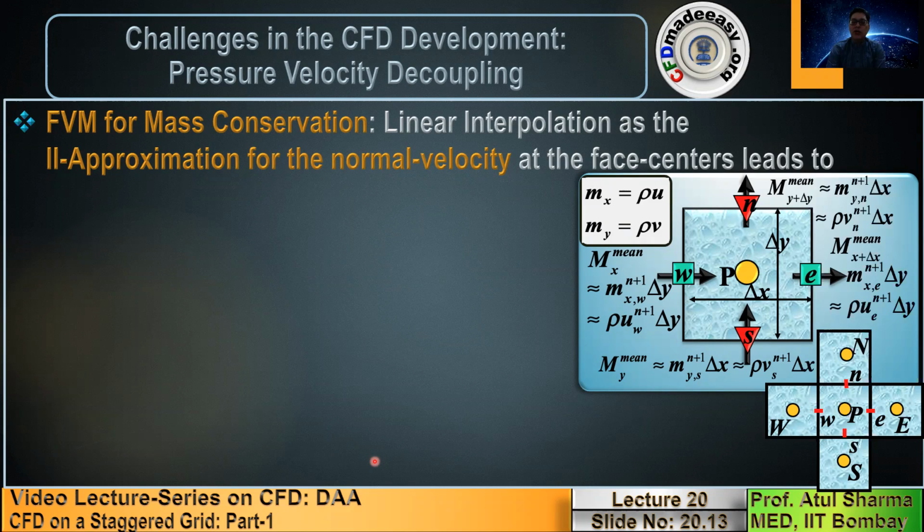So the random motion leads to conduction, and whatever approximation we used for calculating the conduction fluxes, I had mentioned in the previous topic that the idea of molecular transport mechanism based conduction can be easily extended to calculate the viscous forces for momentum conservation.